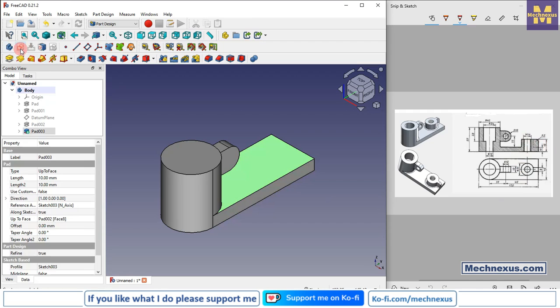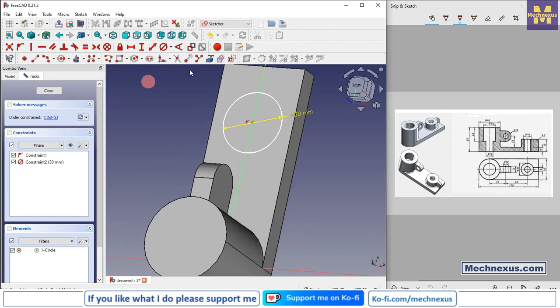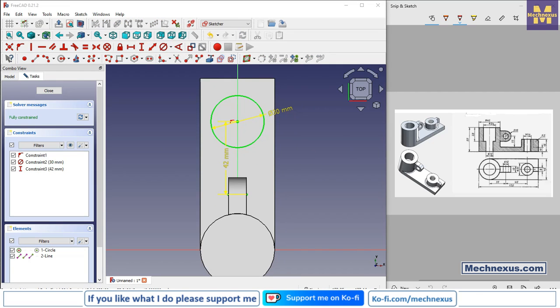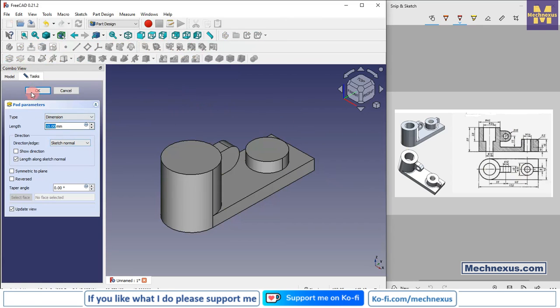The next feature which we are going to make is this circular profile. So select the face, create a sketch, and here I will create a circle, and this circle has a diameter of 30 and position from the axis of 42. So the axis is here, so we will project this edge and select this and this point, or we will switch to the top view, select this point and add a vertical dimension of 42 mm, click on OK, select the sketch and click on extrude and provide 10 mm.